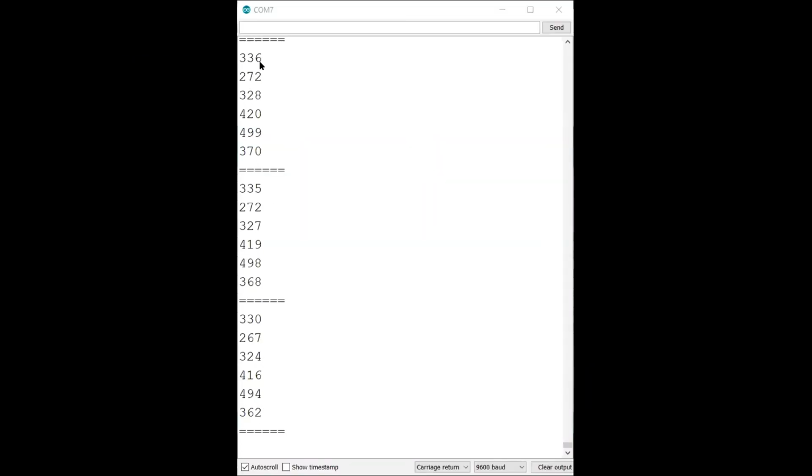So what you're looking at here is this value is the sensor on the one side. Those values there are the middle values. You can also see them over here. And this is scrolling, it's just refreshing the whole time. So it's checking and checking and rechecking. So you can choose which one of these to look at. But what you'll see is now I've moved the robot so that all the sensors are over white, and you'll see those number values are quite high. You'll see those values are actually pretty high.